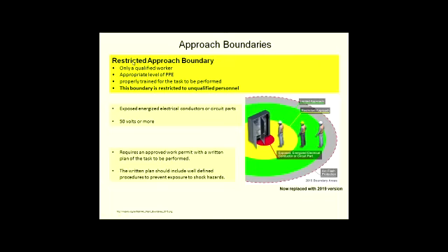Now, let's go to the yellow, the restricted approach boundary: only a qualified person, a worker, with appropriate PPE level, properly trained for the task to be performed.